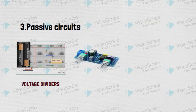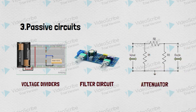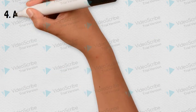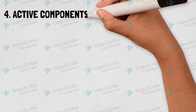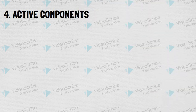Next down the line comes discrete passive circuits, which includes voltage divider, made of resistors. Filter circuits, made of capacitors. Attenuators, made of resistors. These simple circuits itself is not so interesting, but they are vital ingredients of more complex circuits.